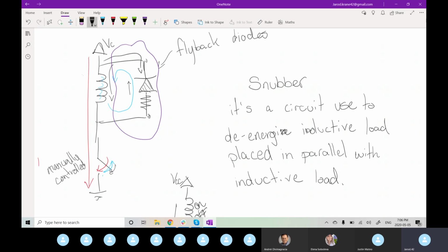Did you sneak in a resistor behind the flyback diode? Yeah. Okay, so is that always going to be the case? No, a lot of times it'll just be the diode, because it has its own internal resistance and it causes a voltage drop on its own.